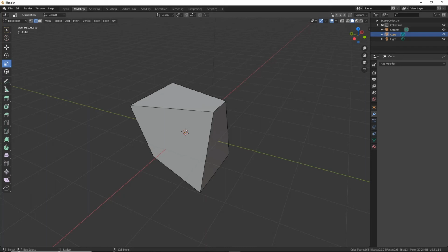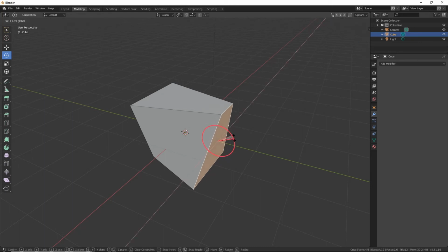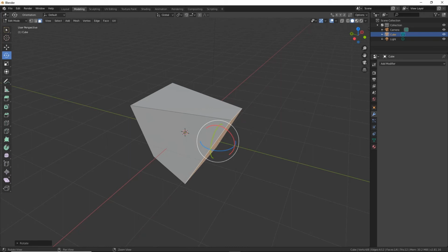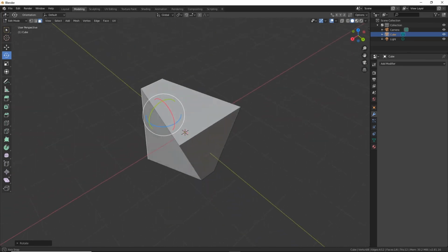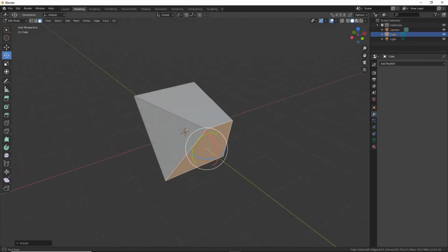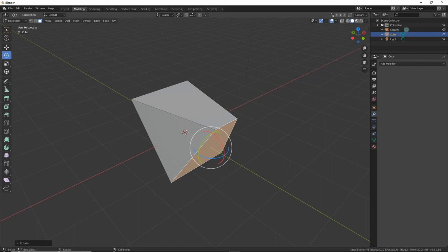So, with the very basics behind us on how we do things, for example, if I just select this polygon by pressing 3 and then press E for the rotate, you can now see how we have all these selections and manipulations and movements really easily and at our fingertips. And again, sorry if this is going fast, but you can rewind if you want to. You can see that we have a lot of control to do things. We can really start making some very complicated shapes.